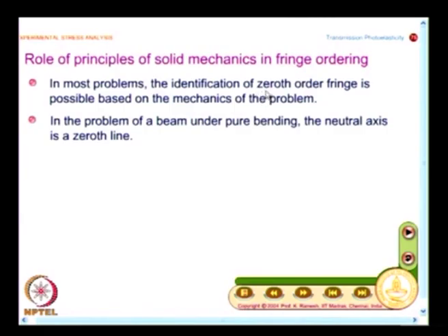See, if I have the zeroth fringe order and if I know the gradient information, it is possible for me to label the fringes, and I can get the gradient information by looking at a color code. And once I mention zeroth fringe order, let us also look at the exceptions, because that was also discussed briefly when we looked at properties of isochromatic and isoclinic fringe fields.